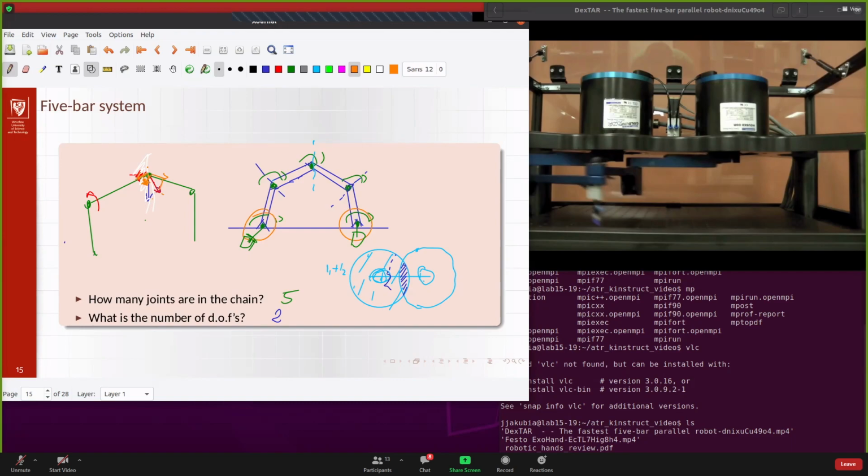So please remember that it's not how it is calculated, because what is wrong in these calculations is that you cannot just start with one part of the arm and then move it back to the second one. In fact, you would need to split the force from the beginning into components for the left and right arm working together. So they need to be balanced from the beginning, but that's mainly the idea to show what's going on.